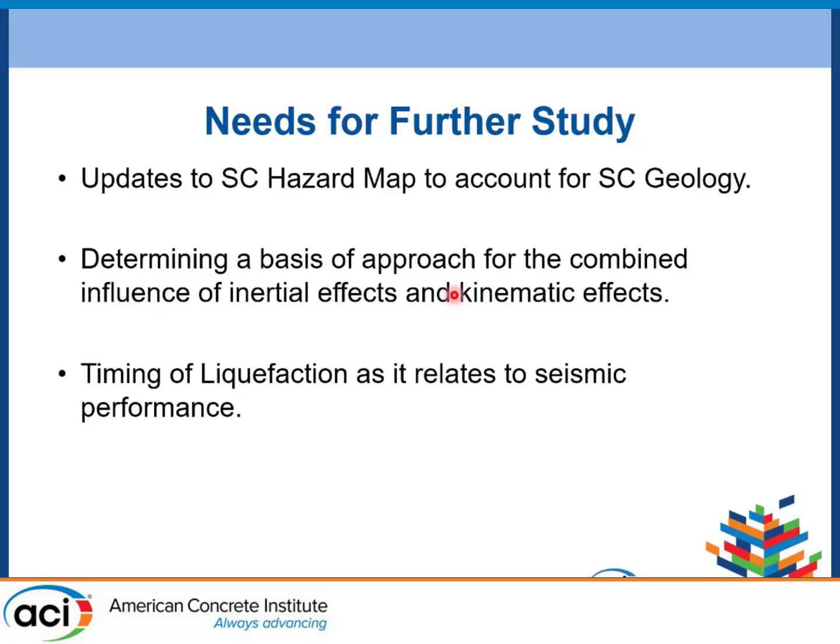But in doing so, there's load imposed on the abutment. Do I need to consider, as a seismic engineer, the entire demand associated with a seismic event, so all the displacement from my seismic event to occur concurrently with the maximum liquefaction load in the substructure? South Carolina doesn't provide any guidance on that, and so we usually are pretty conservative relative to that assumption. But that is guidance that the SDS is lacking and we would love to see.